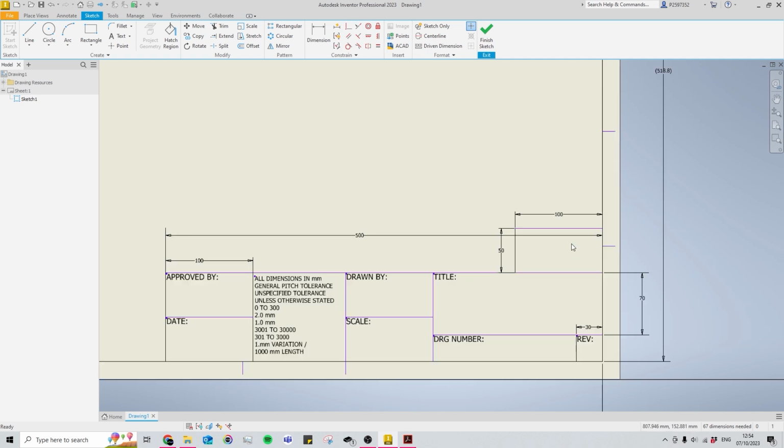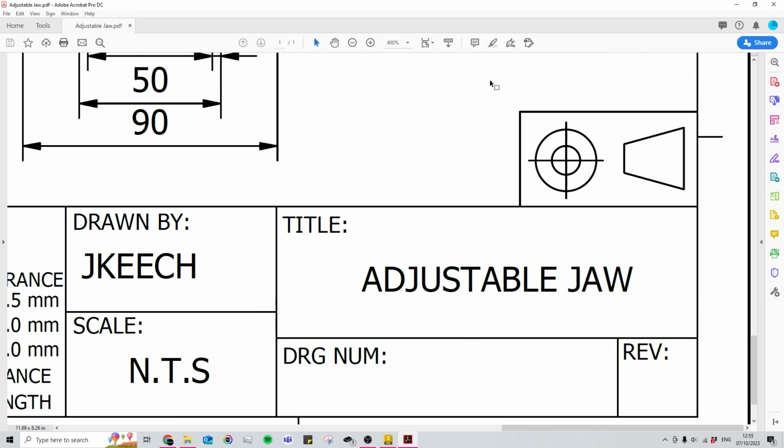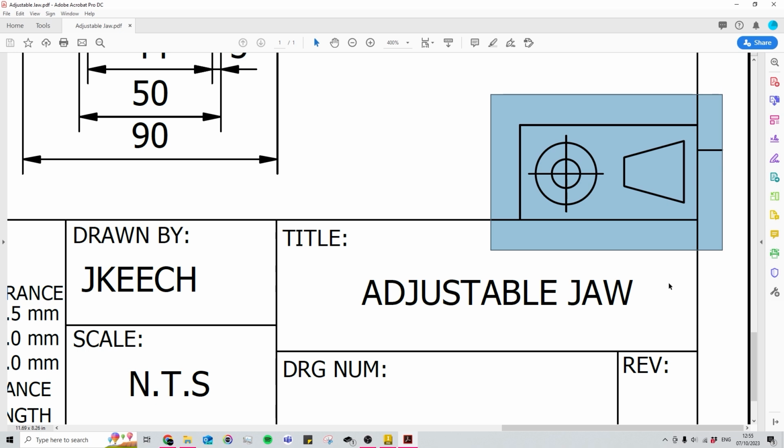The next box is very important though, and that's this one on top. This is known as the projection sketch symbols, which is meant to explain how your drawing is typically displayed in relation to each of the drawing projections. Once again pulling up my standard drawing border, this is what I'm talking about, and with the target on the right hand side rather than this parallelogram and the box on the left, so vice versa, this is meant to indicate a first angle projection.